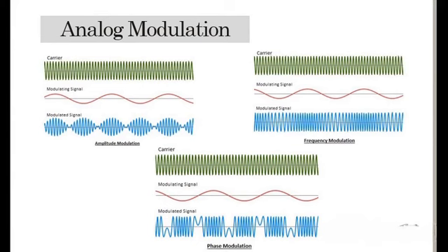The process of modulating signal means putting a low frequency signal on a high frequency carrier signal, the process of varying the RF carrier wave in accordance with the information in a low frequency signal. Analog modulation includes frequency modulation and its advantage of decreasing the noise. There is a significant increase in the signal to noise ratio. We can also reduce the noise by increasing the frequency deviation. It also reduces the interference by the adjacent channel in the band.